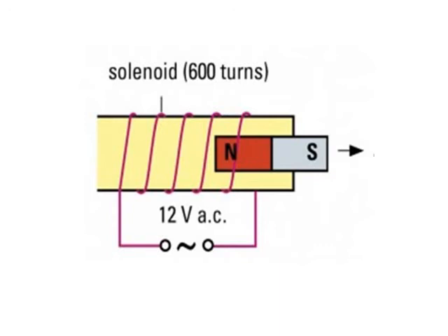The method is, you will use AC current, you will place the magnet inside the solenoid, the cylindrical wire, and you have to withdraw it. Now in the method of magnetization, there is no withdrawal of the magnet, but you have to place the magnet inside the solenoid, provide DC current, and that's it. Now in case of demagnetization, you have to provide AC current, place the magnet in the solenoid, and slowly remove it multiple times, 3, 4, 5, any number of times, and this will help demagnetize the magnet.